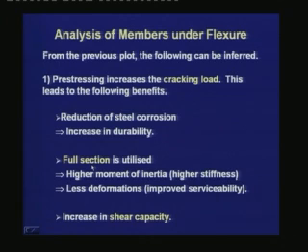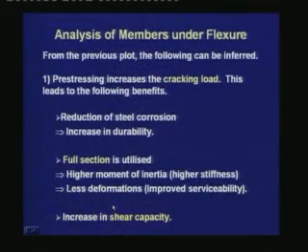Second, full section is utilized. That means we have a higher moment of inertia for a prestressed section corresponding to a reinforced section, which gives higher stiffness, and thus we have less deformations in a prestressed concrete section of equivalent strength, and thus it gives improved serviceability. Also, since the section is uncracked, we have increase in shear capacity for the prestressed section.